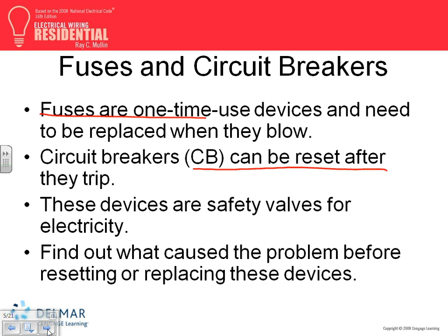Fuses come in so many types, guys, that you can size a fuse so specifically that if you have a short circuit, I guarantee you nothing will happen to this conductor. It's not going to be even damaged. With the circuit breaker, if you have a short circuit, it will interrupt it, but you might have to go change the conductors. Not all of them, but at the end, the terminal right here might burn. So that's an advantage of fuses. Fuses are also current limiting. They have a lot of current limiting fuses.